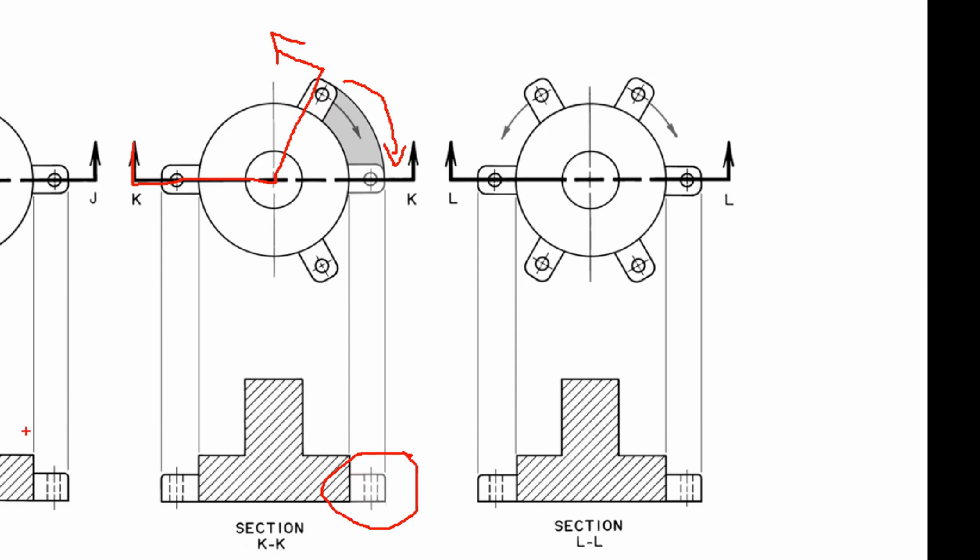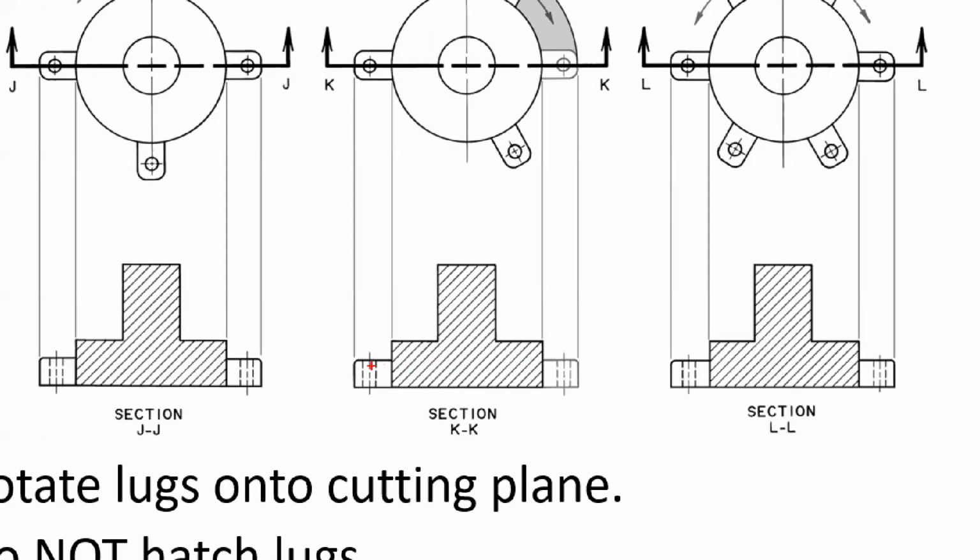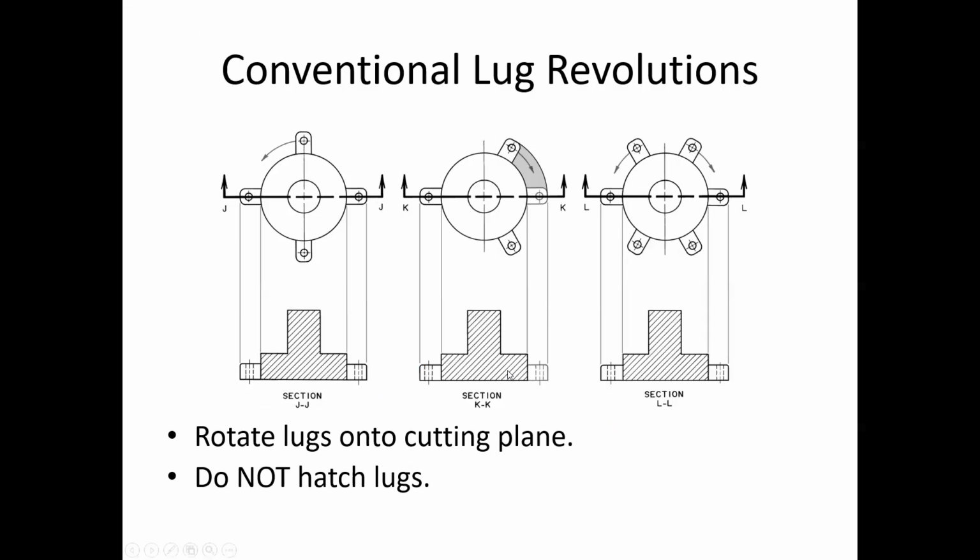So when we draw this out, say we had loads to draw. Do you want hidden lines or object lines? Unless I specifically say otherwise, those would probably be object lines. So we are going to cut through the feature, unlike what they did. It makes more sense to do object lines for cutting. It makes more sense to cut through what you're cutting.